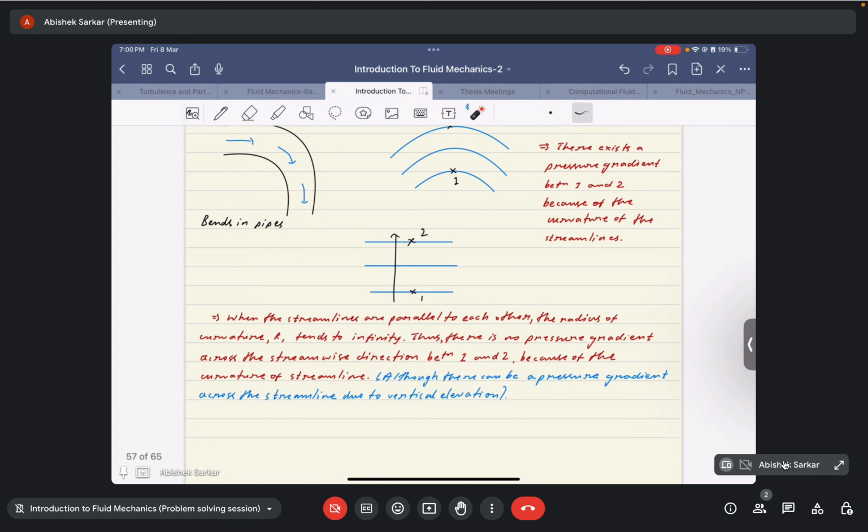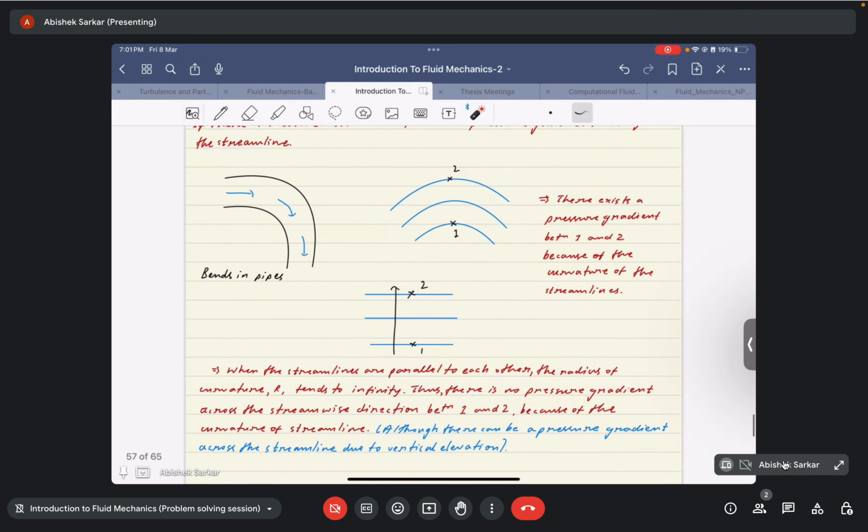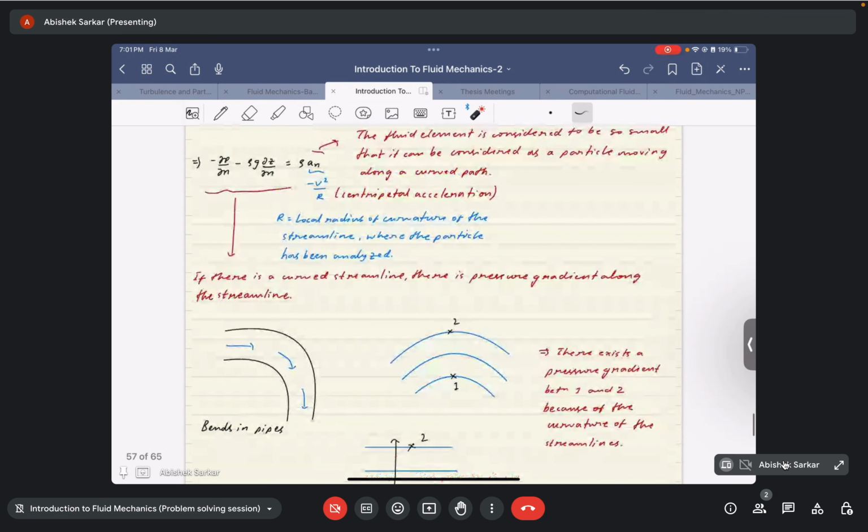I'm mentioning this because these are conceptual questions, like what is the pressure gradient in the case of curved streamlines. You will know that for sure if you remember this equation. Since there is a finite curvature, there is some certain value of r, so there will always be a finite value of the pressure gradient. If r is increasing or r tends to infinity, this term will go to 0, so the pressure gradient itself will be 0. That is what I wanted to mention.